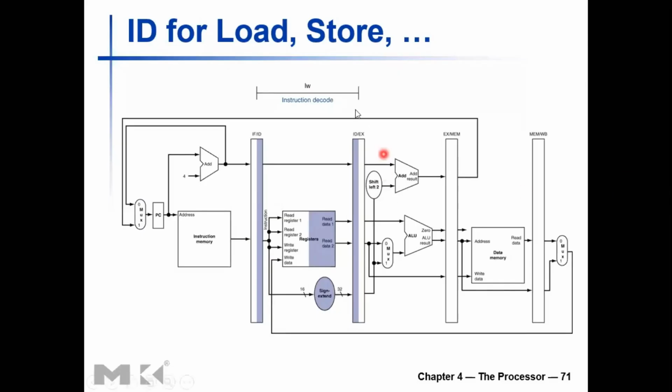Right, so what happens at the beginning of that clock cycle? At the rising edge of that clock cycle, the data to be written into the IFID pipeline register is ready, that is the instruction word and the PC plus 4 value. So those two pieces of information get written into the register as soon as you hit the rising edge of the clock cycle inside this decode stage, right?